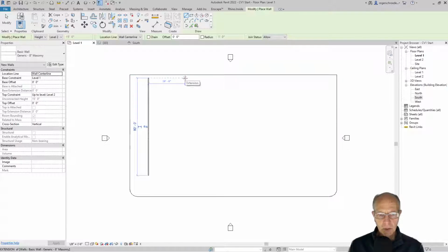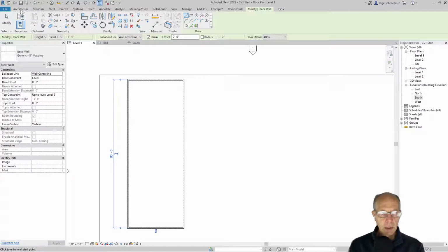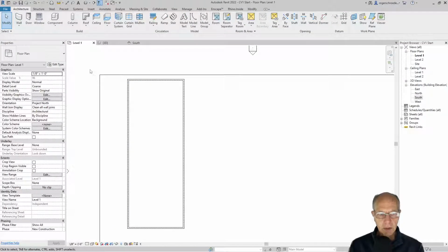I'm going to move over then 30 feet. I'm not on the chain command. Let me click this. I'm sorry. Now I'm going to go back to this wall and pull this over 30 feet. And then when I click on it, and I'll zoom in here, and that'll make it a little easier to get to that 30. Click. I'll drag it down until it's at 80, and you'll notice we get the hinting, and we can carry this all the way through back to this one. And when we're done, we can click the modify, and that'll take us out of the construction mode.